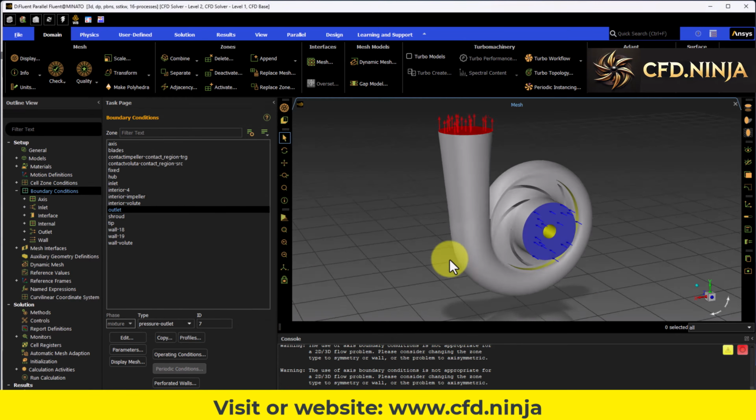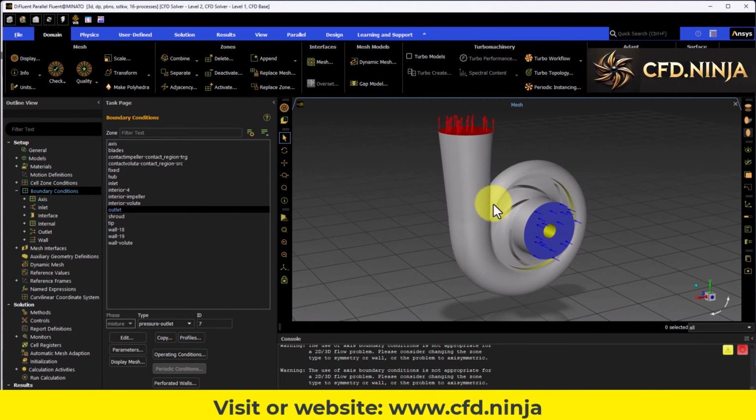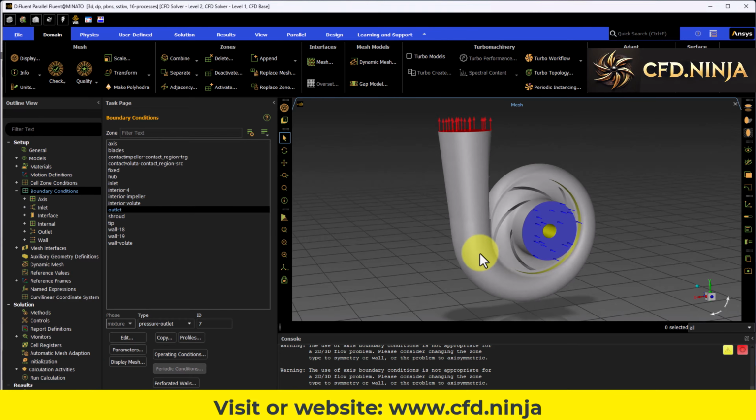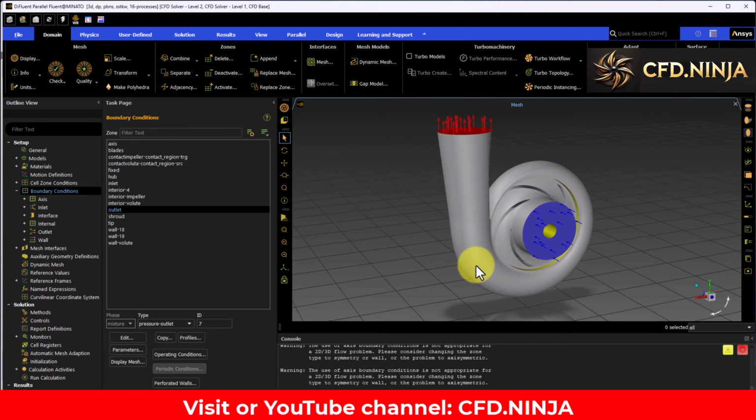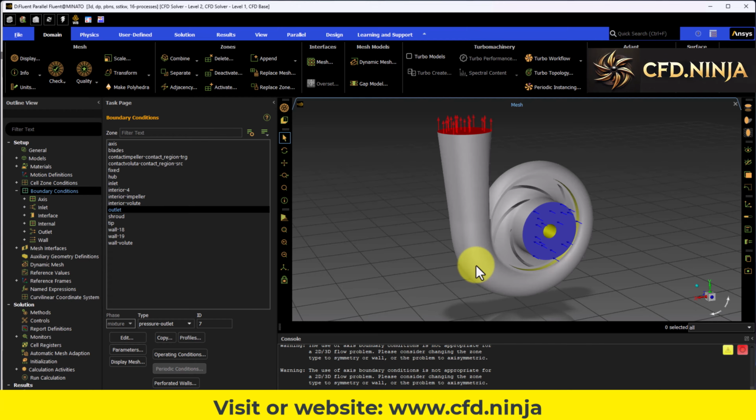Very well. Now I'm going to focus on the impeller to generate the boundary conditions. The impeller obviously has to be moving. However, this simulation is stationary. That is, we are going to create a fictitious movement in order to obtain convergence quickly. If we wanted to do a transient simulation, this would take a lot of time, especially because of the Courant number that we would have to calculate.